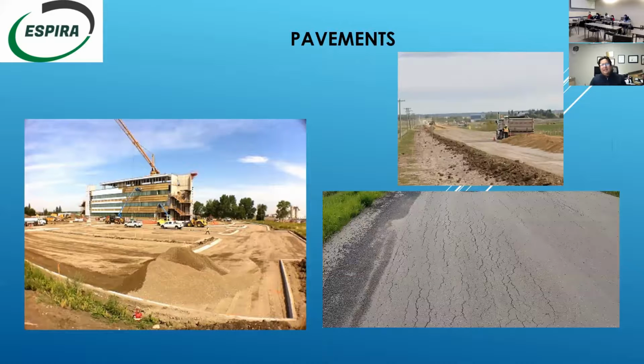The pavements typically have a few options. For example, light duty. It could be light duty structure or heavy duty structure. These are general descriptions with actual loads estimated. Other projects such as highways should have design criteria specified, such as equivalent single axle load or ESAL, and vehicle weights as per Alberta Transportation, AASHTO, ACI. Different counties have different specifications. City of Edmonton, for example, has design and construction standards. And Fort McMurray, Wood Buffalo would also have their own standards.